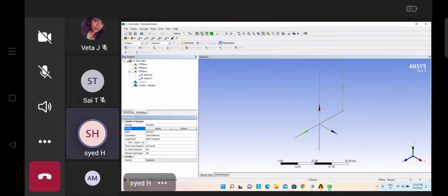Actually, this option we use for creating helical shapes. If you are creating anything on a helix, like a spring, use this option. Both the sketches, the line as well as the profile, should be lying on the same plane, but in different sketches. Now both the things I selected here. Now I am going for the option twist.